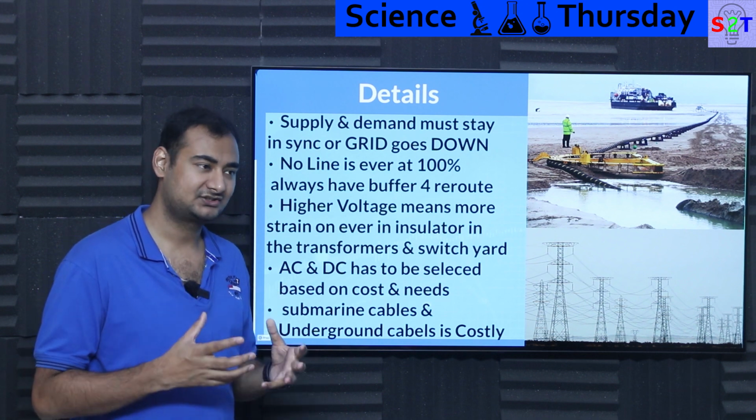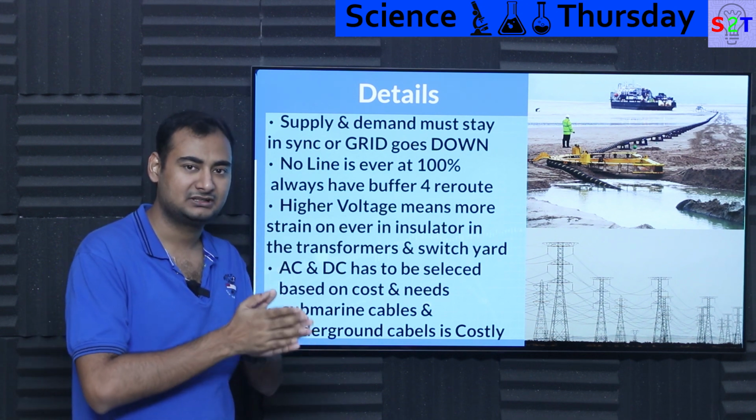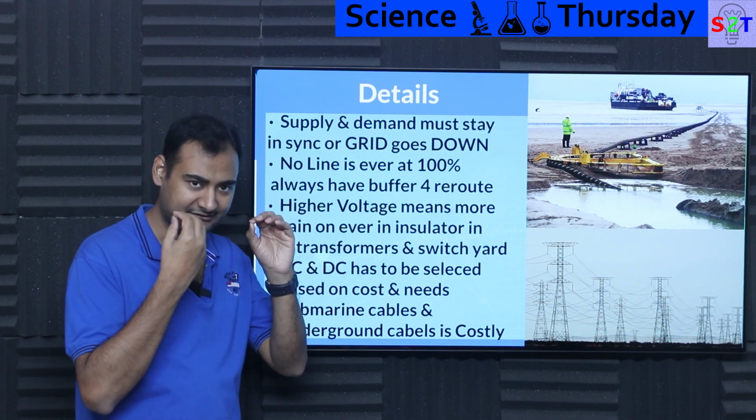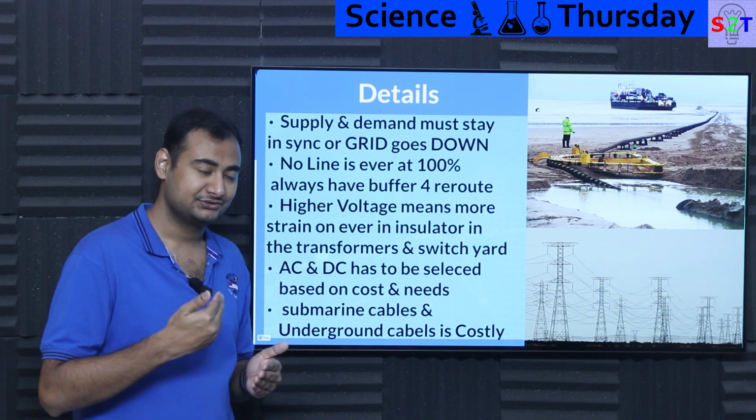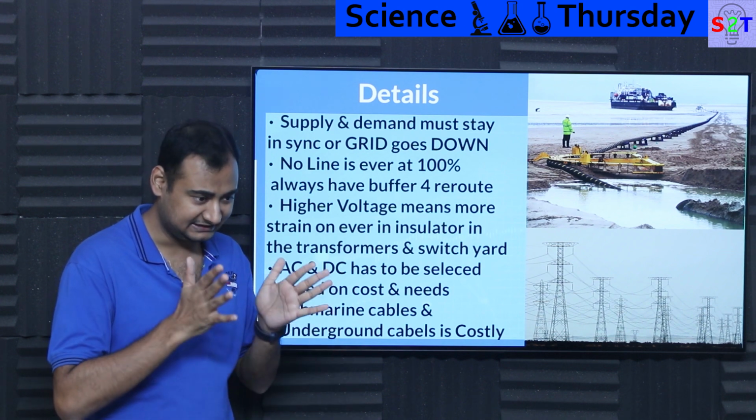And where is the biggest strain on this? Transformers. Each transformer has windings. Those windings have to be as tight as possible. Consequence, they do not have enough space for insulating materials. So insulation is really not magical there. That's the upper limit.